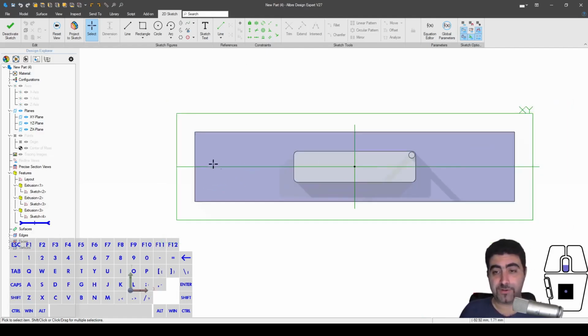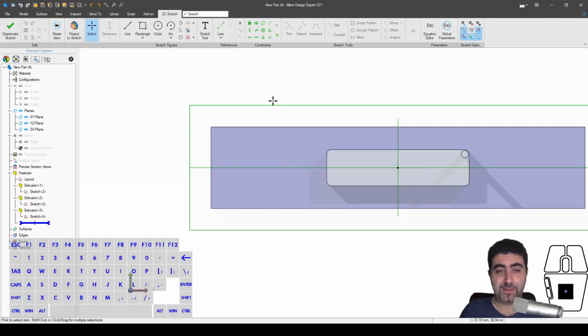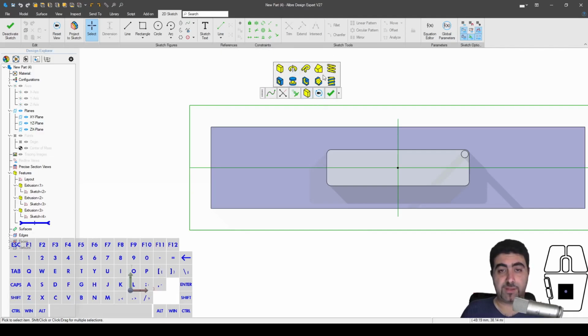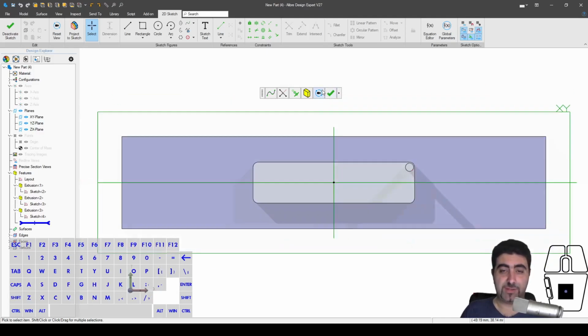So when you're in Sketch, Alibre can open an in context bar with any commands that make sense. There are two ways to do it. You can either click on blank space, you see it popped up as soon as I move my mouse, it fades out. Or what Harold told me, which is a lot more useful, you can just hit your space bar. So right now I can either select a sketch entity, trim or something, my constraints, I can start a feature, or I can orient to the sketch plane. I'm sure you can imagine that this is very useful.